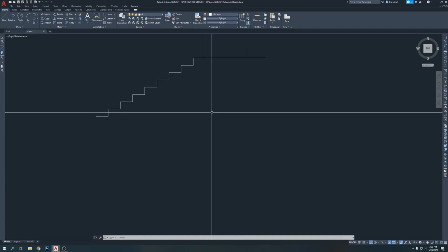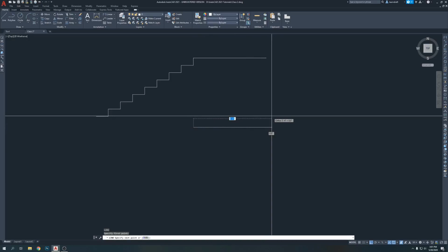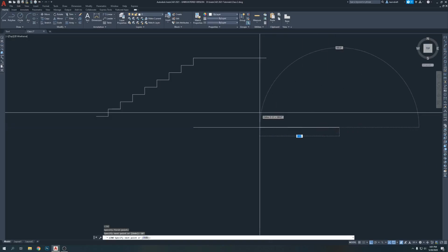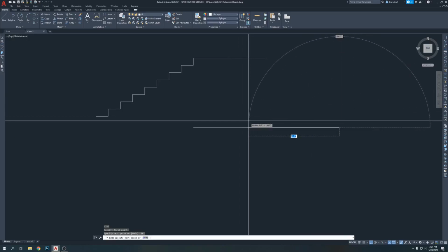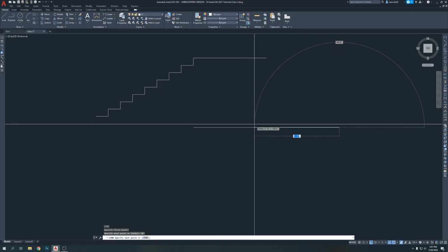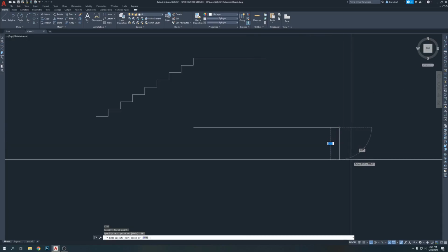Extend. Okay, so I'm going to type L, enter, click, go this way, let's say 10 feet from the keyboard, which is next to the enter, and press enter. When your cursor is here and it shows on the right side this point, like a circle, and some dimension below, that means your endpoint is here. If you practice line a lot, you're going to find it easily.